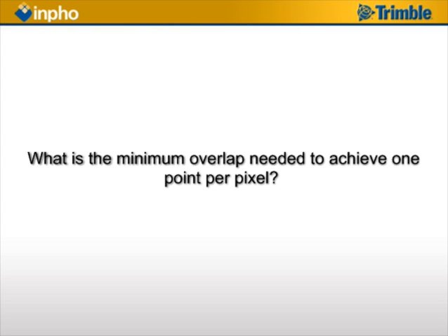And actually, that 60 by 60% is necessary just to look into those narrow streets. So it's not a necessity from a point of matching. It's just a necessity to really have visible areas available. So if I have a densely built up area and tiny streets, and I really want to extract the points on the ground, then you need that 60 by 60% overlap.